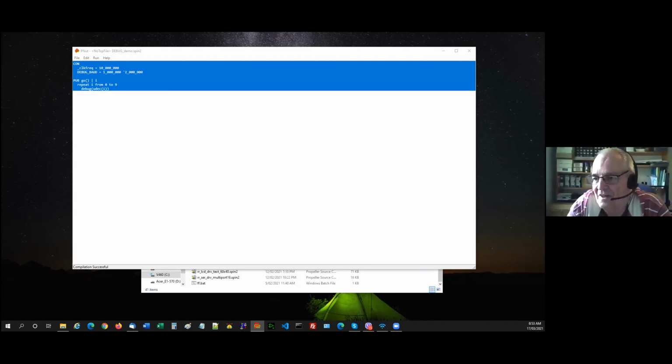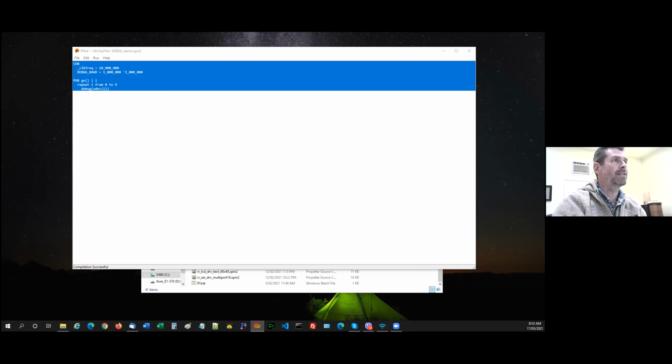Yeah, there's some suspicion that the CP2102 won't run at 2 megabaud, but I have to say that I can download my CPM code, which I think is about 70 kbytes, at 2 megabaud using load P2 without any problems at all. So maybe there's some problem coming back the other way. I don't know, but I think it's running on my system right here.